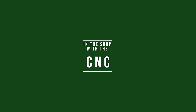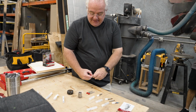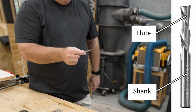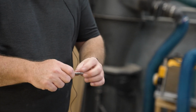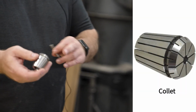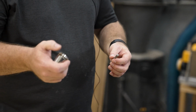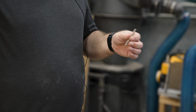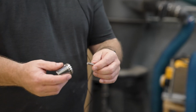Before we actually start working on the machine, we're going to talk about bits. They come in all shapes and sizes. The most common bit you're going to use is a 1/4 inch shank with two flutes at the end, so there are 2 cutting surfaces. This is what one of them looks like. They go into the machine in what's called a collet, and the collet has to match the size of the shank. We have 1/8 inch, 1/4 and 1/2 inch collets. Those are the most common sizes, so think about that when you're buying bits. Most of what you're going to buy will be 1/4 inch shanks. It fits in the collet like that.